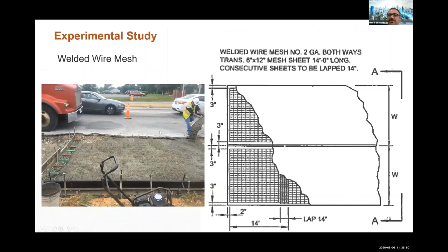I mean, of course, for the shrinkage and temperature reason, that can be justified, but for the strength-wise, we can't justify that, because if that reinforcement goes near the neutral axis, this is not something that we, as a designer, can expect.